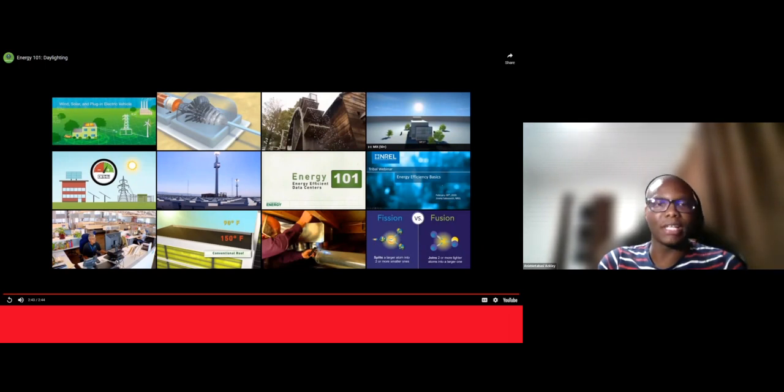The key things to note from that video is that west and east facing windows could be prone to glare issues. And this is due to the low angle of the sun in the mornings and also in the late afternoons. So when designing your windows on these orientations, strategies such as using a window hood or looking for ways to shade could be helpful to optimize daylighting.